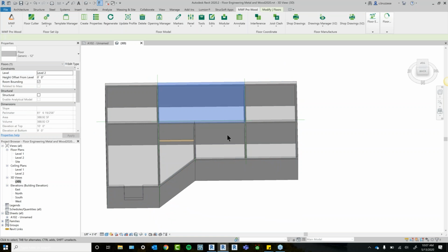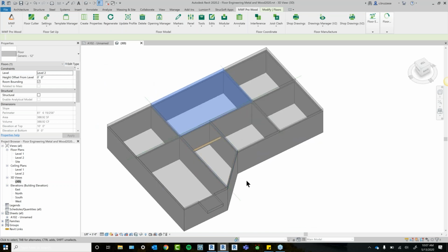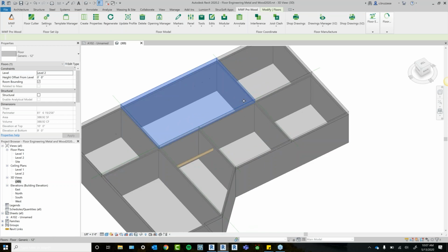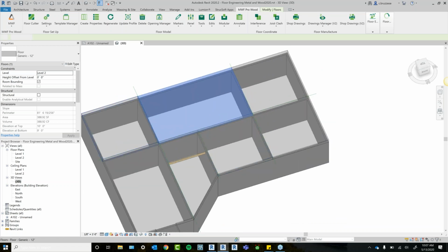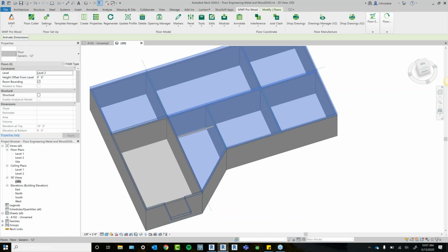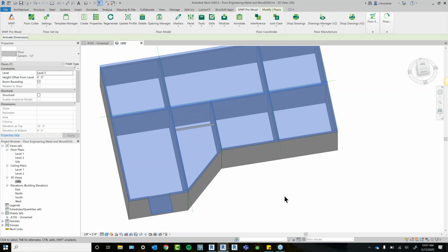The next things in terms of general setup that I'll highlight, since we are talking more about analysis today, is that when you are running these floor panels, you're going to want to make sure that you have some kind of supports wherever those joists will run. I've got walls today. You could put in beams. That will work just fine. Basically, as long as the joists will have some type of support to pick up during analysis. And I know I am supporting them underneath the floor, but if you are realistically running these with hangers, then as long as the floor is connecting into the wall, there's no issues there.